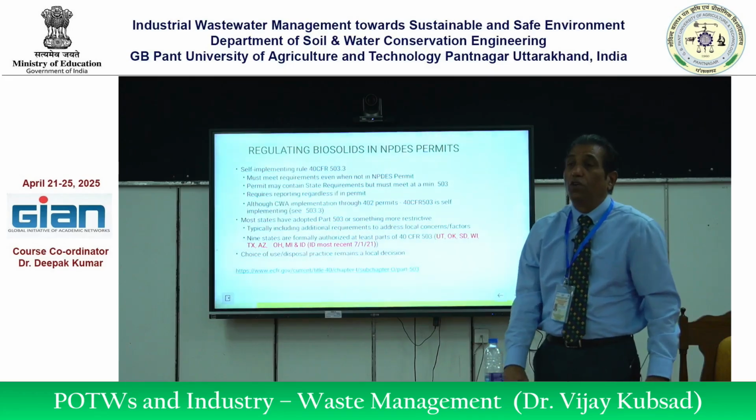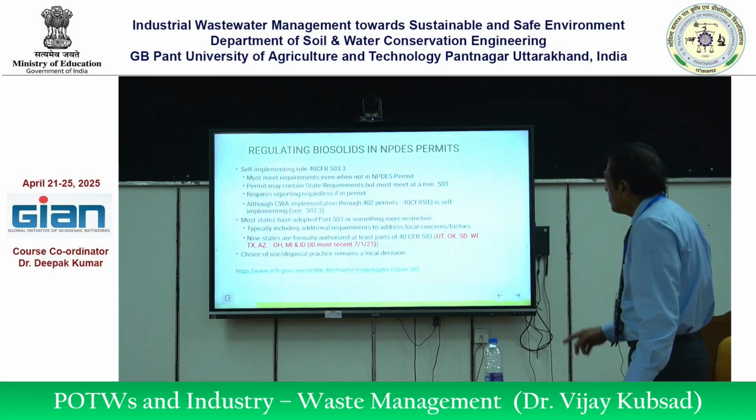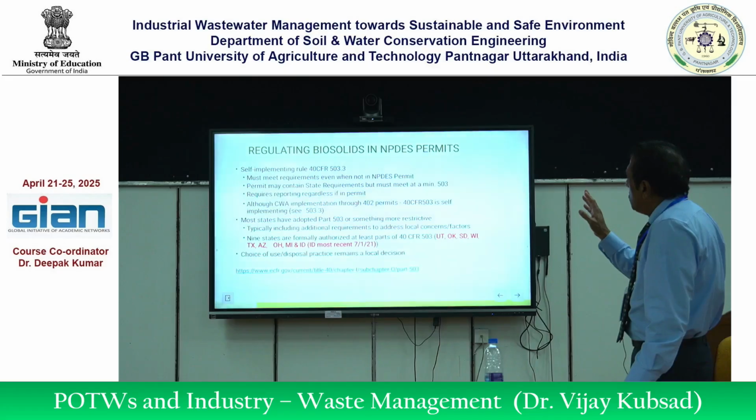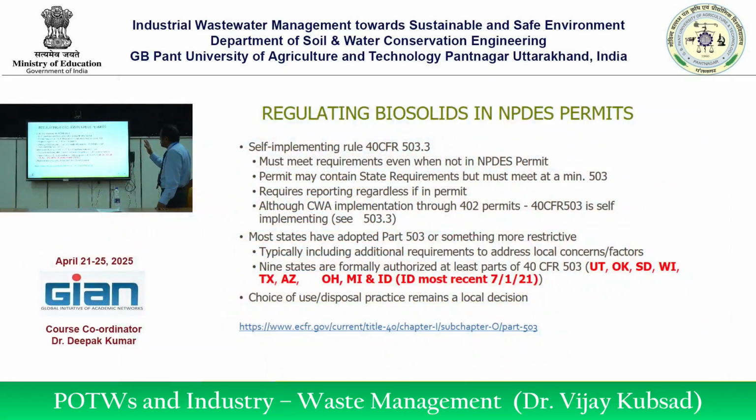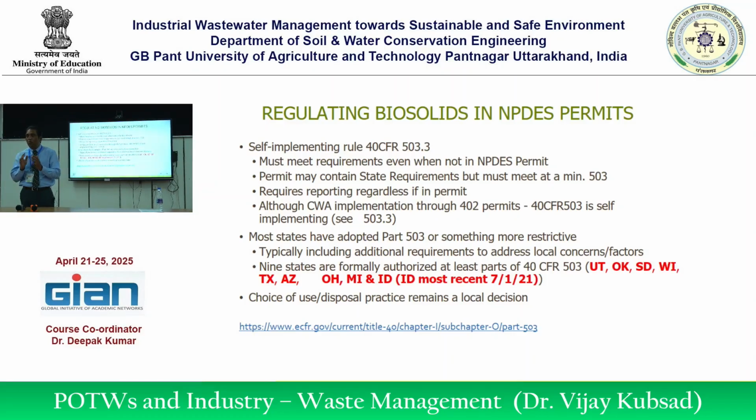Then that can be further developed into a manual, right? So for the implementation of these permits, it is not only important to take care of the wastewater, the sludge produced from the wastewater is also important. There are regulations for that. Depending upon the volume, you have to evaluate whether they need an authorization requirement, and how to dispose of that sludge.